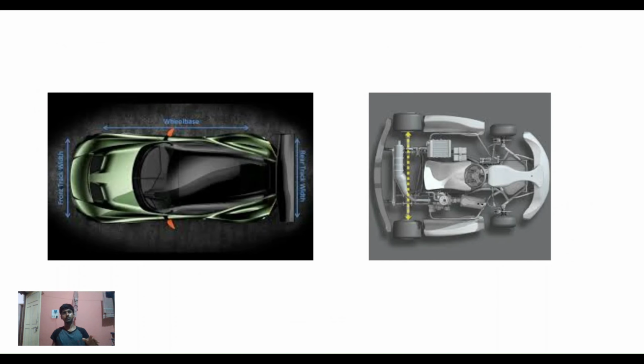At the same time, this centrifugal force torque is countered by the normal reaction produced by the outer tires. These two torques cancel each other out, which helps the automobile stay rooted on the ground and complete the turn. That's why having a wider track width is necessary.